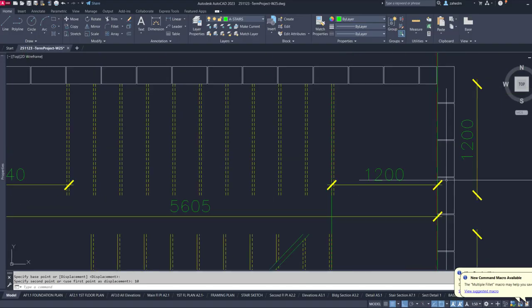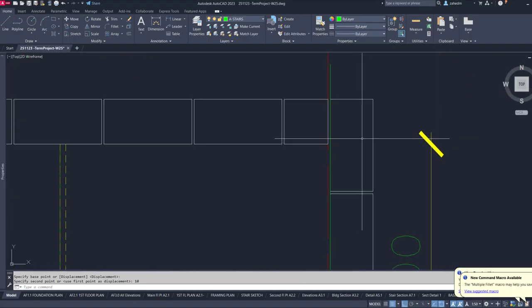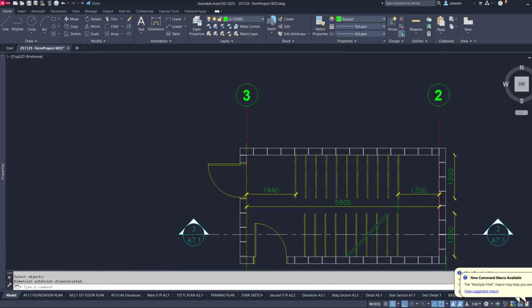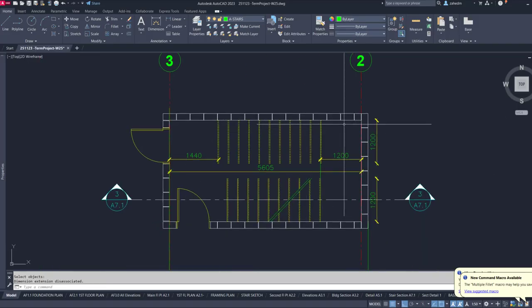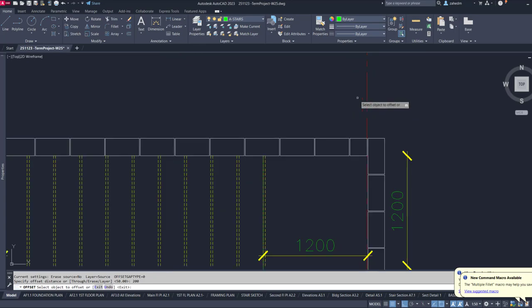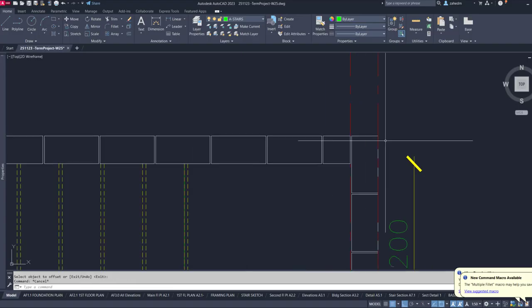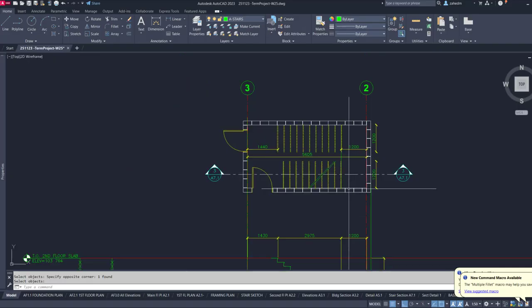Now this is where exactly the numbers should be, because that was the convention from the beginning in the assignment, as we've been working on working drawings 3, so the students are aware of what we've been doing. 10 is the offset, so when we do the offset of 200, that has to fit on the exterior face of the concrete block wall, which falls exactly where it needs to be, because the concrete block wall is 190, it's not 200. That's the beauty of it.